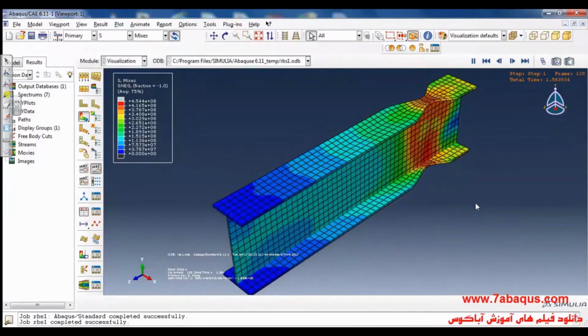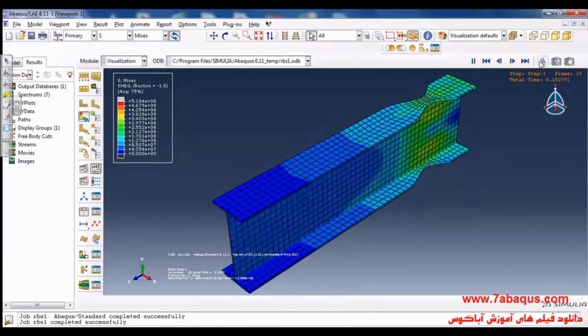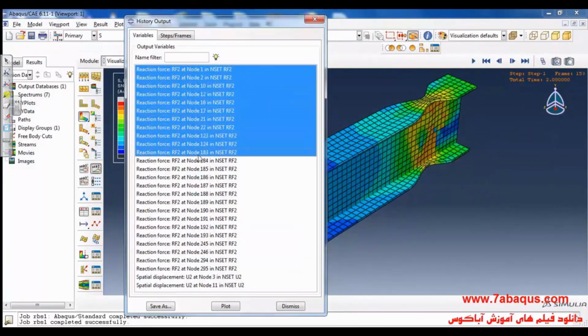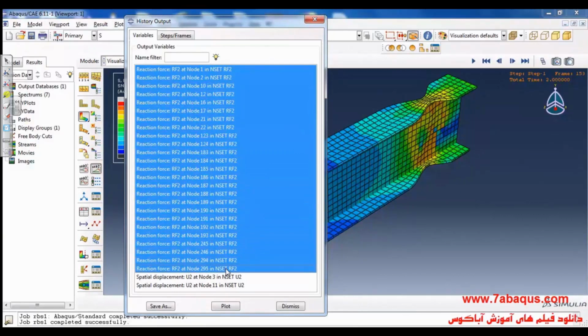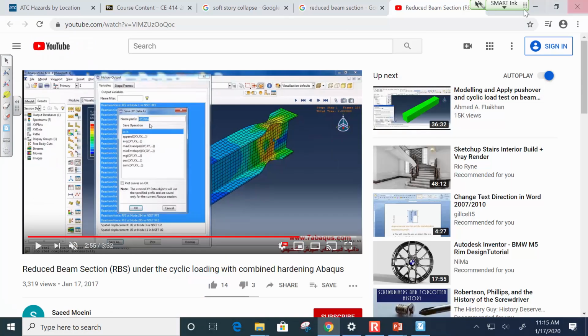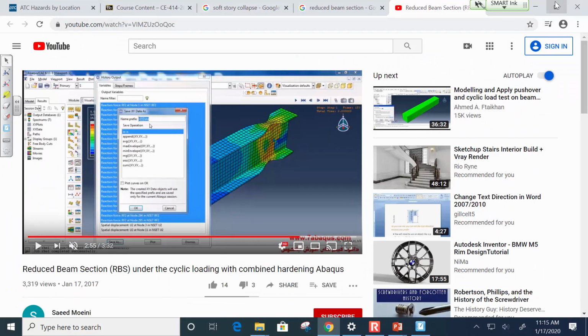Like back in World War II, when the cities in Europe were getting shelled, one of the things that they would do is they would build these cages out of steel inside their houses, and they would get inside the cage, and the steel would absorb all the energy from the blast, and they would survive. Steel is a very, very ductile material. If you look at its ability to withstand all of that energy, it's a really optimal choice for earthquake design, just because of its ductility.